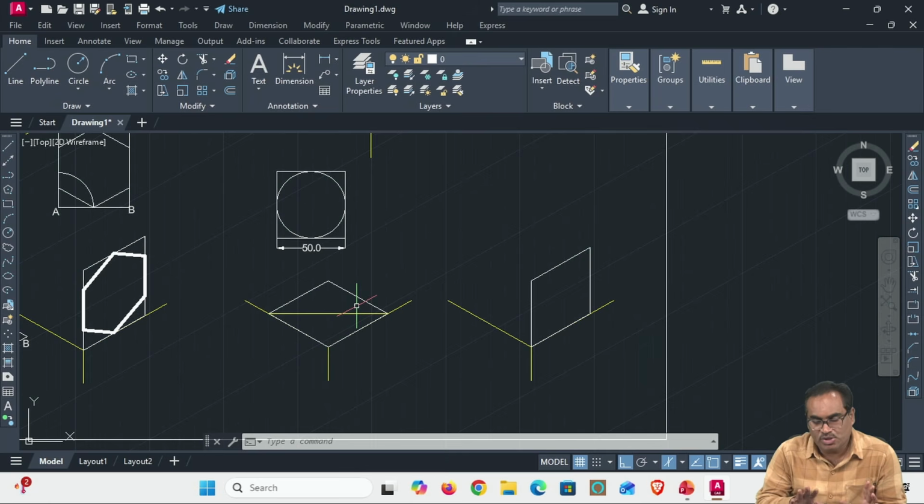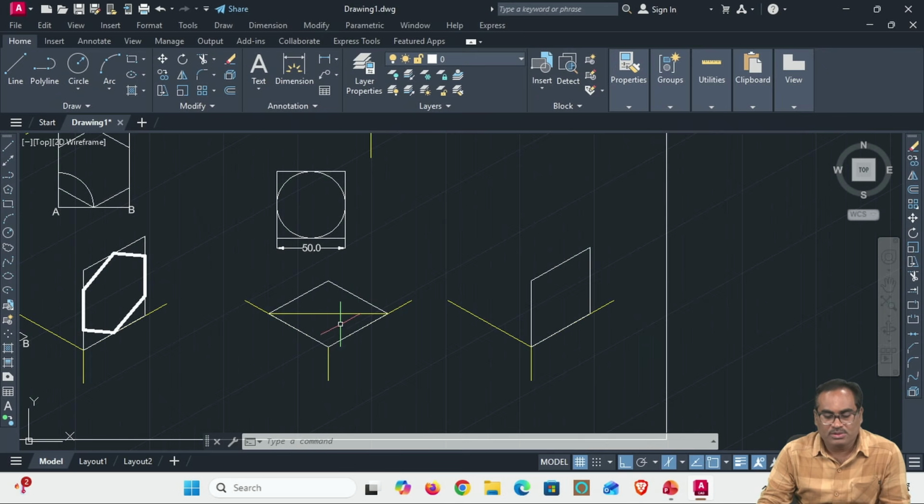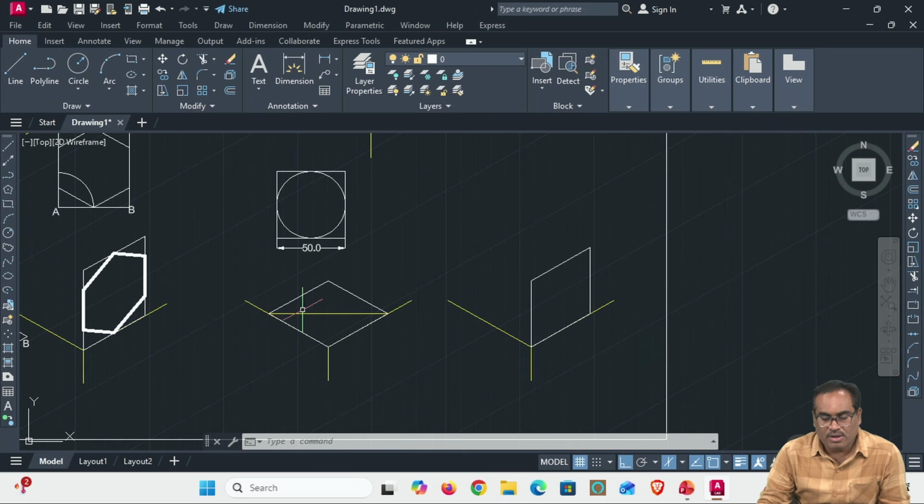But here in isometric view, the dimensions are the same, but you'll have one diagonal longer and one diagonal shorter, and the adjacent sides also differ. In a normal view, adjacent sides of a square are each 90 degrees, but here two adjacent sides are less than 90 and the other two are more than 90. So this is what isometric looks like, like a rhombus. Right, so what I can do is take the longer diagonal.